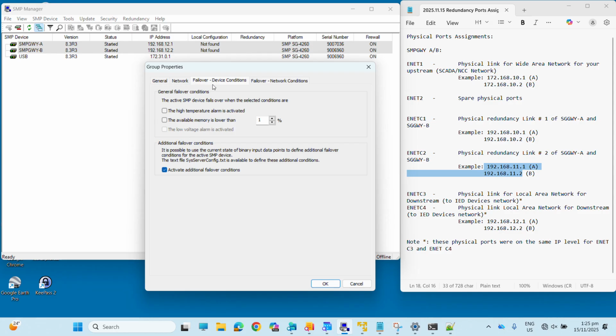But we have one question: as gateway A is the priority one, is that the master, and gateway B the slave? No, there's no such concept of master and slave, it's actually hot and standby. If for some reason the standby one becomes faulty, there should be some sort of alert signal. Yes, there's an indication in your logs. You can see that in your logs.